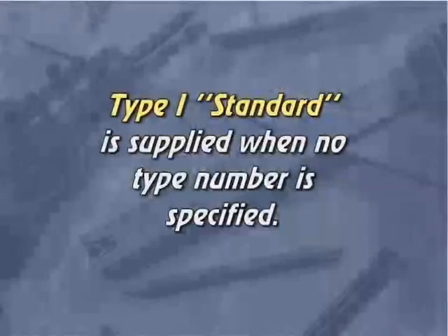Now, there's certain conditions when you use a different type of cement, and you would tell the mixing plant which type to use, or they would say, okay, we're going to change your type of cement because you have certain conditions. If you got into type 2, which is sometimes called the modified or the moderate, even though we have none in the book there, that generates less heat and takes a little longer time to cure.